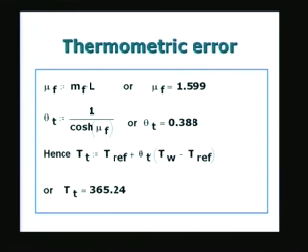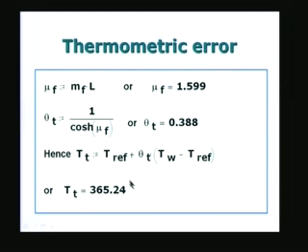between these two. So, if I want to use this particular arrangement for the measurement of temperature of a fluid flowing through a tube, I will have to use this as a correction to the measured value. Because I am going to measure this value, this is what the temperature is indicated by the thermocouple. So, I am going to add this thermometer error, which is calculated based on this kind of analysis, and correct for the temperature.